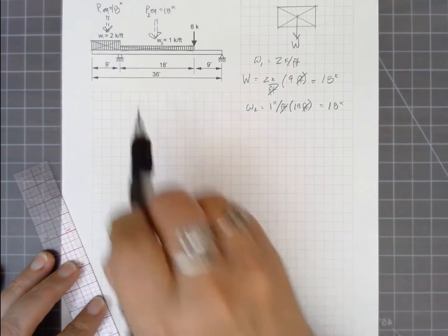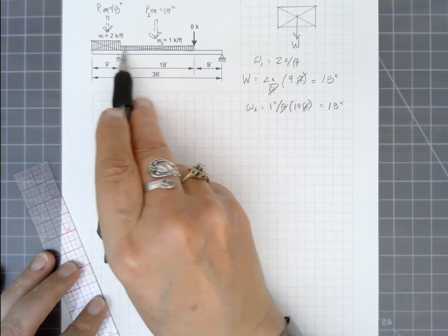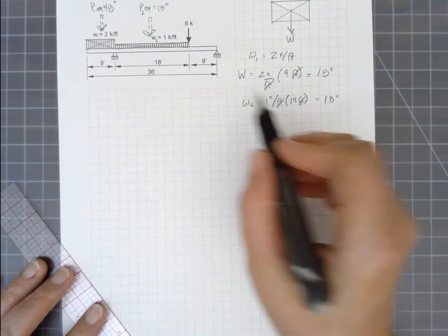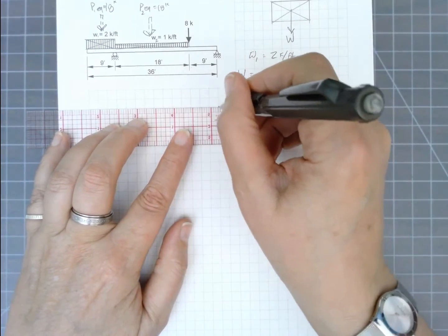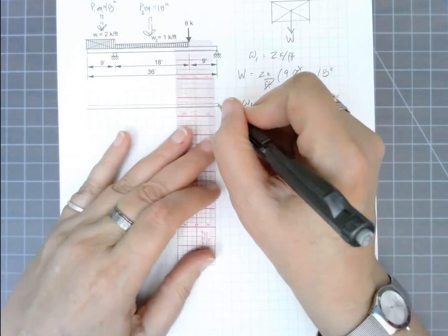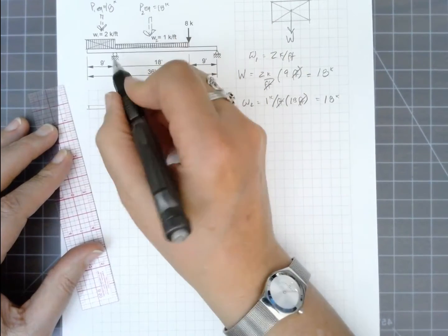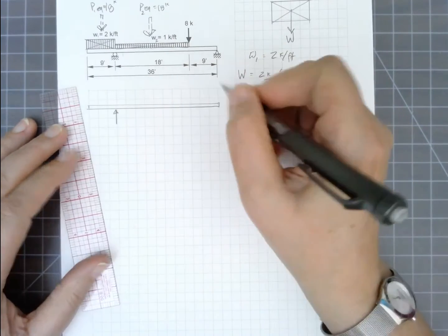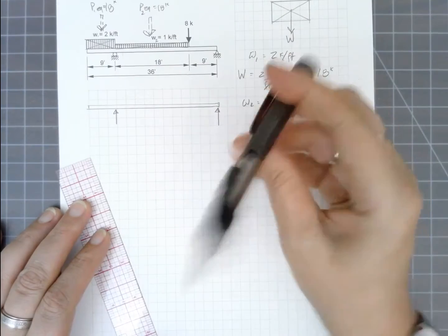Now it's important to understand the reason I call this equivalent is that the behavior of the beam will be very different when it's loaded as a distributed load versus a concentrated load. So let's redraw this now as the equivalent beam, just to make things really, really clear. Now the roller support can only support a force perpendicular to its surface, so I'm going to place that with an arrow, and I'll put a vertical arrow in for the right-hand reaction.